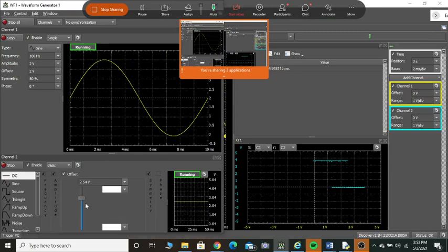Okay, VTH and VTL, do they keep changing? Can you see? Is it moving? Can you people observe this? See now, if I'm reducing that, is it also reducing? So if it is 0.57, this is okay. Corresponding to that, I'm going to get the waveforms. You can see it's almost this is 1.72. This is half of that. This is 1.8. This is 0.9. And of course, if it is 3 volt, this is 1.5. Correct?